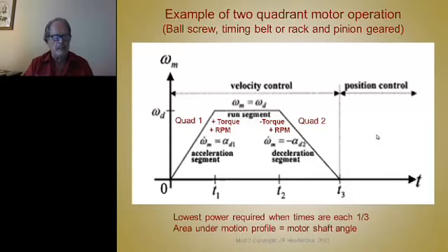So for part of that time you're accelerating, that's positive torque and speed. That's all right. Now here we're up to a speed. And by the way, this sort of a trapezoid is a very close approximation to the shape of a parabola. I guess I should have drawn one on top of here. But for an angular positional move, a parabolic move is the best, but a trapezoid makes it easy to control.